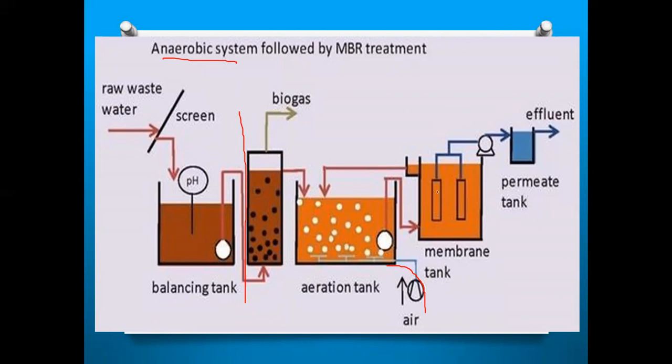In this membrane, you are having different filters. The filters will collect the waste material, and the water is going through the pump. It is passing into the effluent, meaning the treated wastewater is coming out of this effluent tank, right? The biomass is prepared in this tank. What are the results of this one? The methane and carbon dioxide, in this anaerobic process.